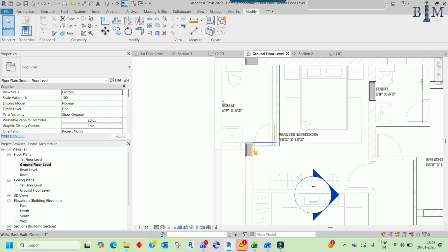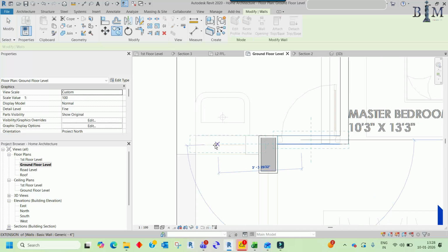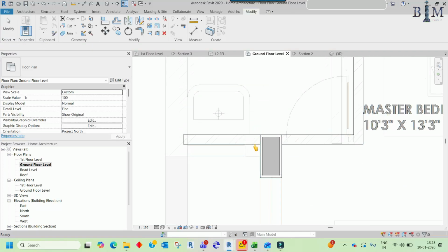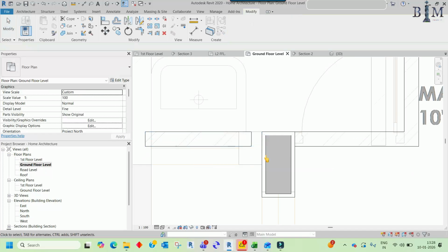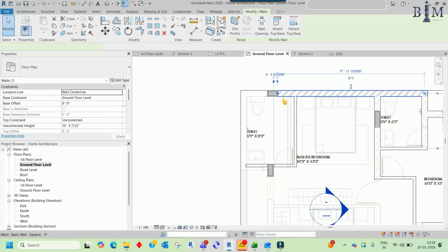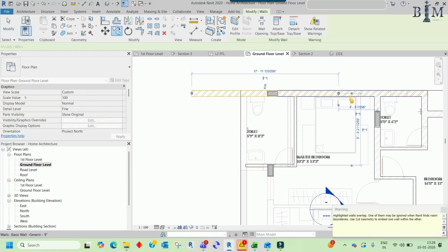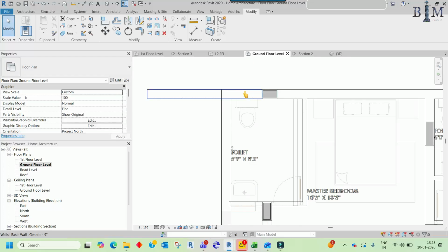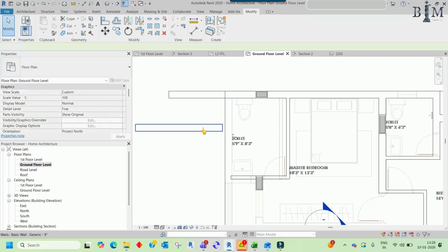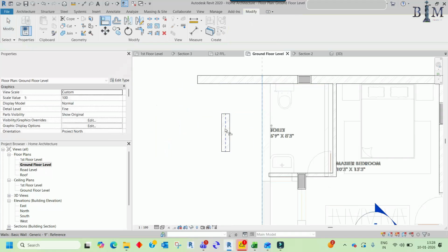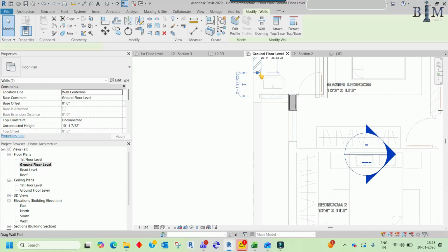Okay, so the door will be the next touch, no problem. For now, fix the wall. The wall should be aligned up to the column, and there will be another wall, so copy the wall. Copy the wall and align it up to this column, then copy another wall, rotate the wall up to this, align it and trim the corner.